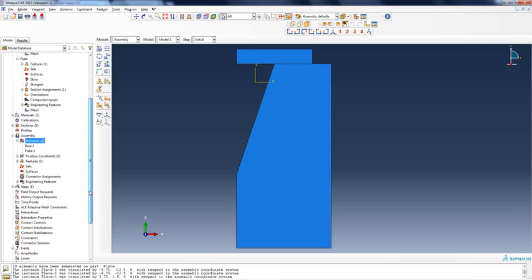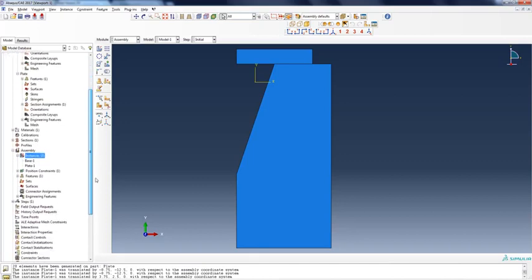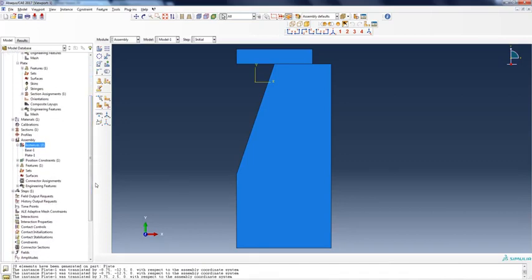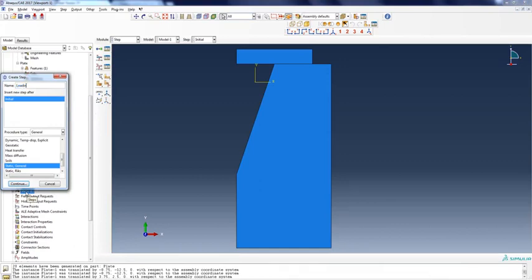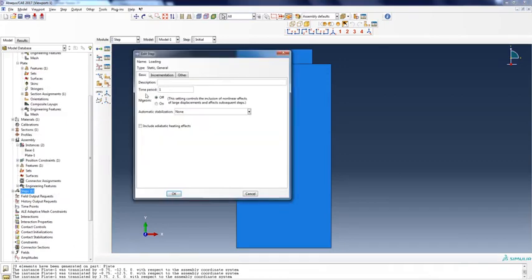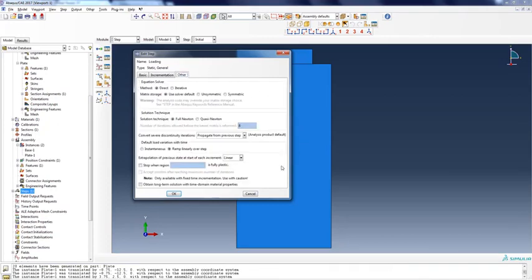Now, after putting the two under assembly, we can start to define boundary conditions. And before that, we should create the step. So because this is a geometric nonlinear problem, we turn it on. Here we have plasticity. We might want to use smaller increments. And yeah, we'll leave this here. Again, in the first exercise, we learned the influence of this option, and I would like to turn it off so that we use the real full Newton.